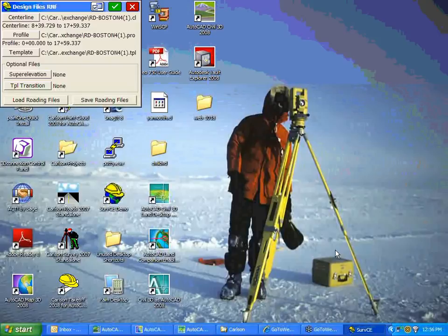They're proxies, like when you vote. A proxy vote is a stand-in. These are stand-in objects. They're just holding the place, because what you really need, if you have proxies, is to install the object enabler so that you'll see the actual object, let's say the contour object. And again, if you're then working with Carlson, you would want to convert it to a polyline.